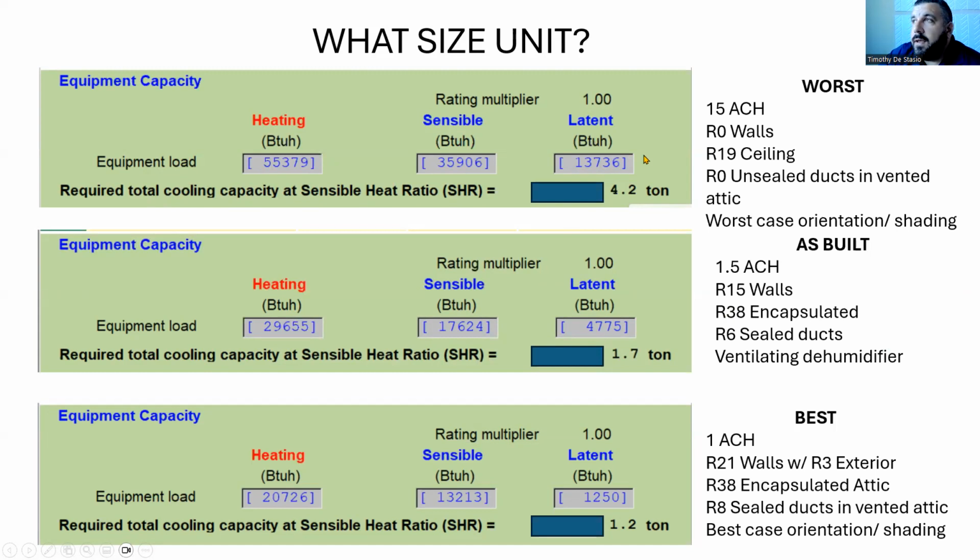So it just goes to show you that we need to do a heat load calculation, we cannot rely on assumptions. Now, I do want to say that after you've done thousands of load calculations like I've done, and you've been in the same climate for your entire career, you can start seeing patterns, and you start seeing the same house over and over again. And you start understanding what things drive a load and what things don't really drive a load.